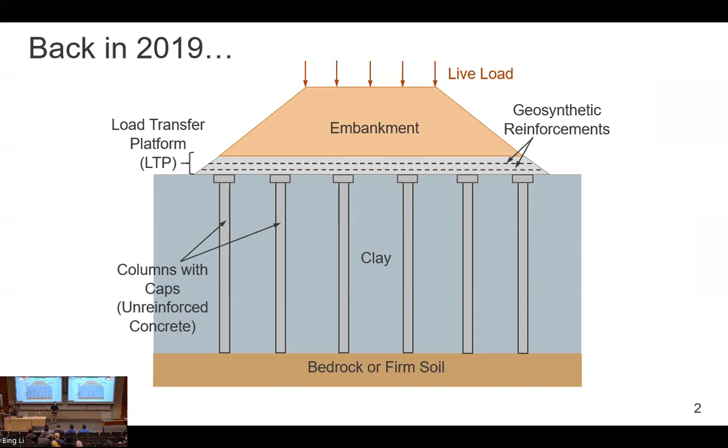So if your piles are extending to a very competent layer, such as bedrock or firm soil, as I've indicated, usually settlement is not too great a concern. And I think what people would do in this case is figure out the load distribution between the soft soil and the column, and then they may want to do an analysis of the individual column itself. Now, there are cases where the columns may be floating. By floating, I mean that they may not be extending to a competent stratum. In that case, it's actually very hard to do the analysis. People may just resort to numerical analysis.